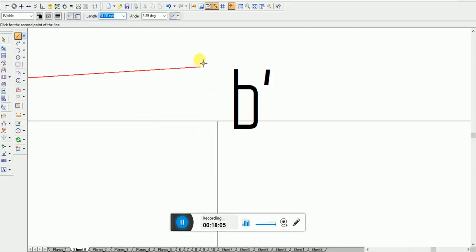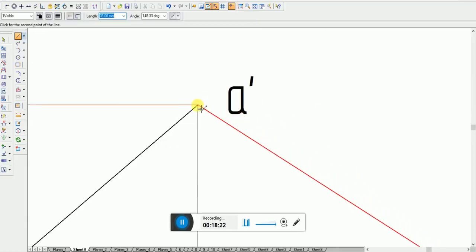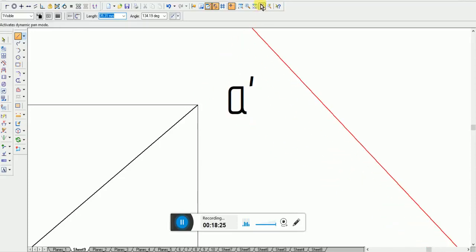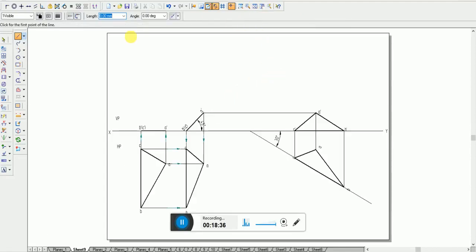See, that line keeps continuing because when you select the zoom area, for a moment that line will not be visible to you, but the moment you switch off the zoom area, see, now we are very much precise. Now again go back to this point. You need not zoom in and zoom out every time. There is also an option called pan area, which you can use in order to just move it. Once you're done with this, again go here. Here you can see something called a leader. That itself is the tool used in order to draw these arrow marks.